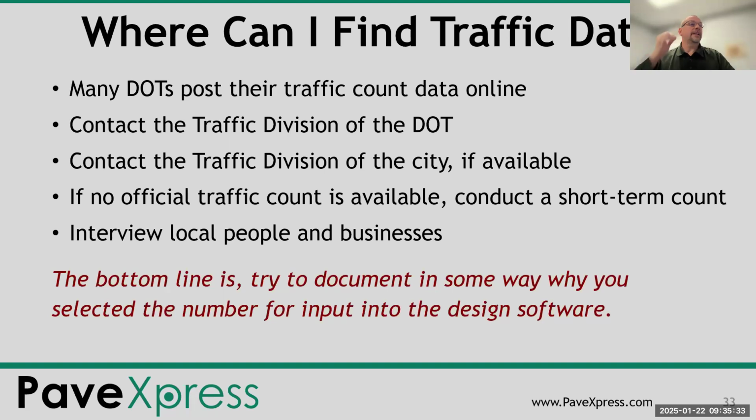If no official traffic count is available, you can conduct a short-term count. I know that was kind of popular back when we were in college. We'd get hired on to do traffic counts for people, go sit at corners and interview local people and businesses. The bottom line is you want to try to document in some way what you've selected as your traffic inputs.